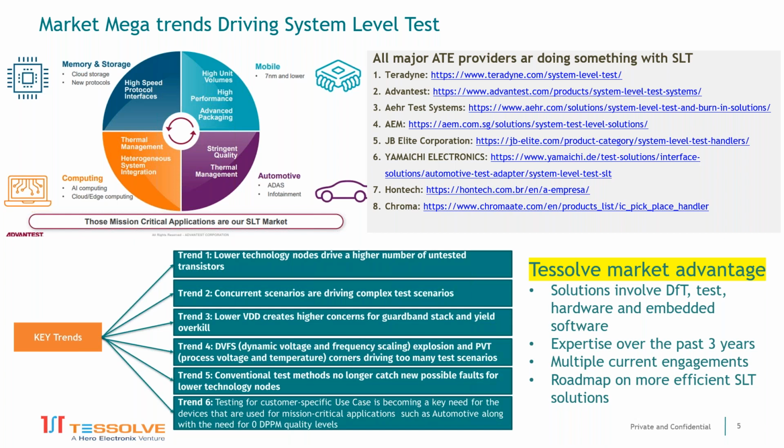So they avoid high volume SLT by using the SLT as a coverage analysis, if you like. And any extra faults they find, they push back into the ATE.